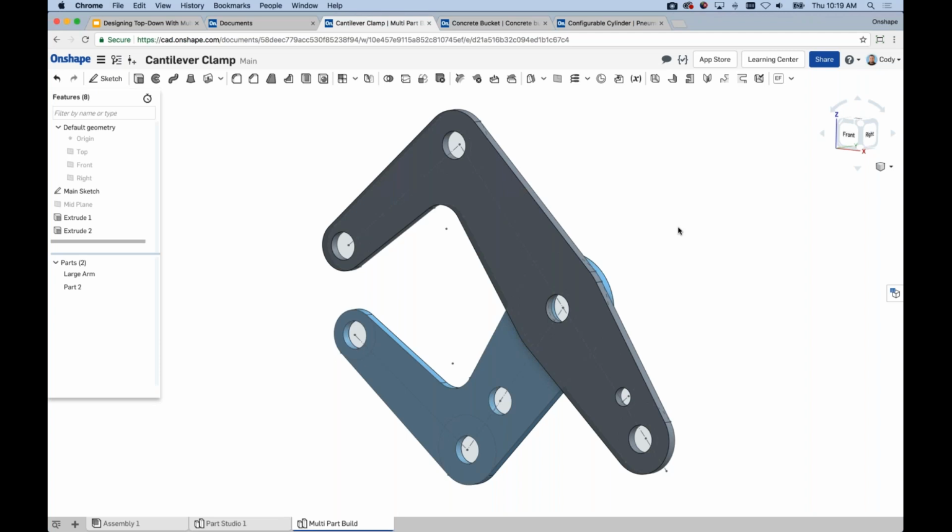So for a large number of parts, a lot of positioning of parts, where you have to put parts in certain positions that are very specific, moving parts around in a part studio is not a fun process. It's transforms, it's establishing custom-made connectors and so on. So it's much easier to move parts around in the assembly and just design in context.